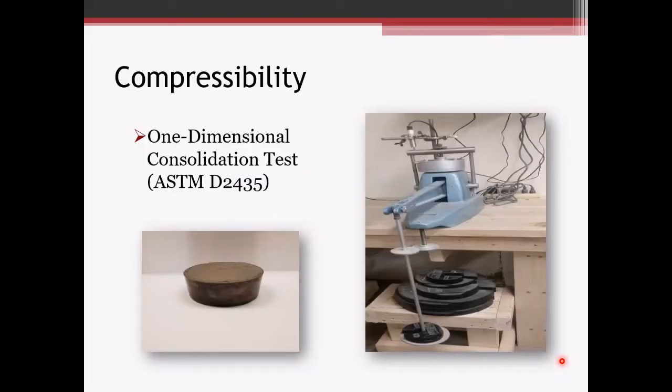For the compressibility test, the mainstay is the one-dimensional consolidation test. This is primarily used to evaluate the magnitude and rate of settlement of a saturated cohesive soil.